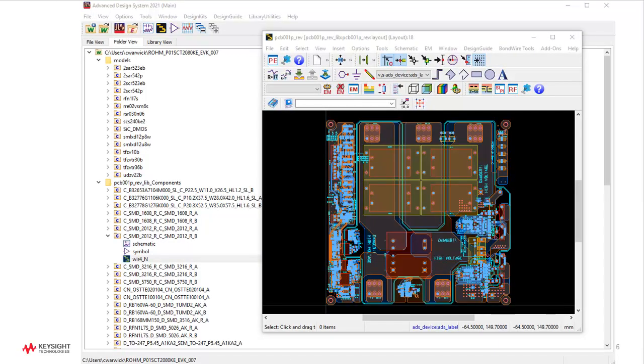Now contrast that situation with using the digital twin, the virtual prototype, which goes along with that user guide. Everything's pre-built for you. The schematics are created because the components are loaded onto the printed circuit board. We've already imported the layout from the Enterprise PCB tool.